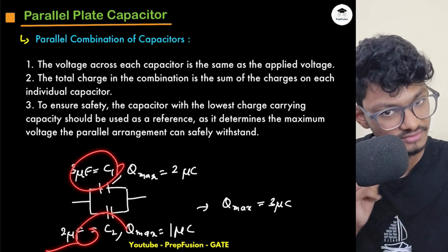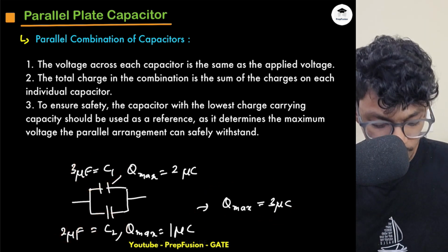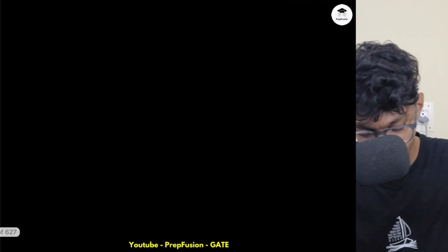The capacitances I have been given are fixed. So according to the capacitance, the charge will get distributed. You chose the maximum limits for all of them. So you chose 3 microcoulomb. If I choose 3 microcoulomb, how will the charge get divided?